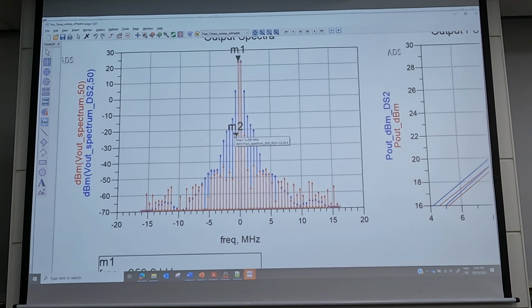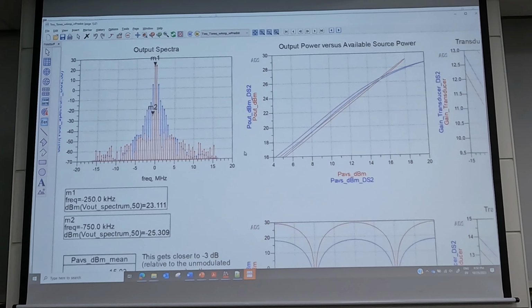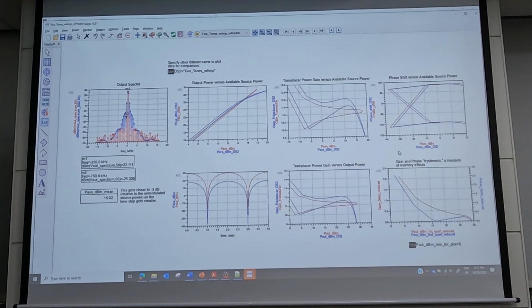Ideally, these two terms, the third order intermod terms, would be identical. That would indicate there's no memory. And this is showing data versus time, actually. So the larger the spread is, the more memory you have present. Okay. Any questions about this?